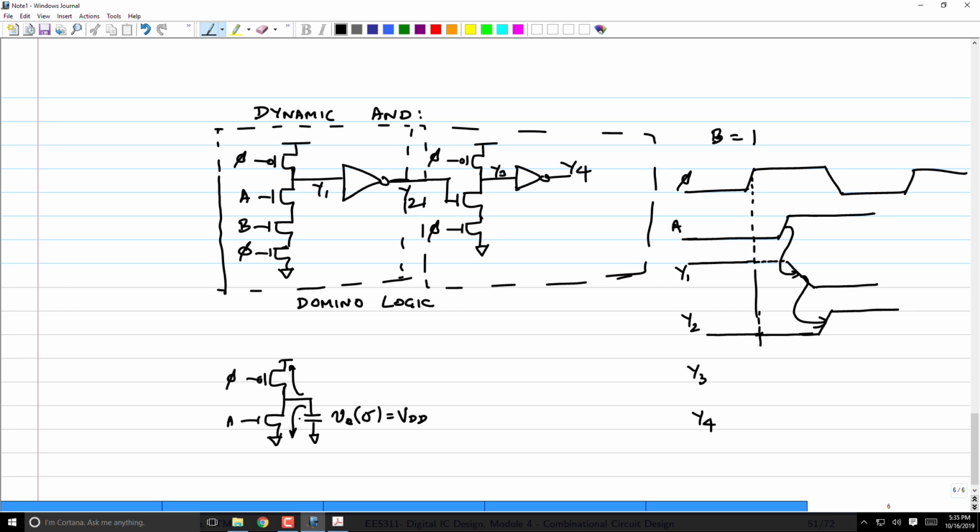Usually you operate this at gigahertz or megahertz. It can't discharge that fast because leakage is such a small current. But you're right that because of this, I cannot operate a dynamic circuit at any frequency. Static CMOS logic, I can operate at any frequency. It will work. Dynamic logic, it cannot work because of this issue. Okay?